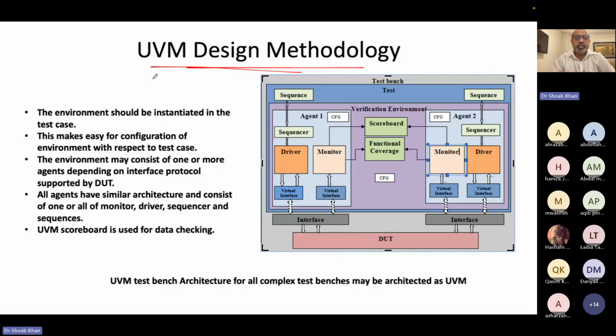It is a standard because it provides you with a framework to learn and to have your device in. Then you have your interfaces, and then you have drivers, and you generate all the sequences for your test. There's a sequencer through a driver, through this interface, that gives inputs to the device under test, and brings those back to the monitor.